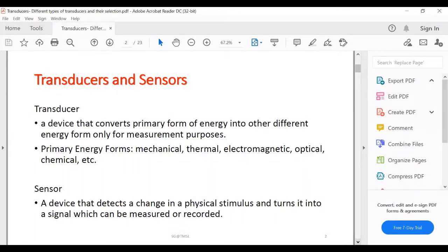As long as the transduction function is non-ambiguous, it is possible to determine the magnitude of the input variable from the electrical output signal, at least in principle. Certain other variables may interfere with this transduction process, such as the hysteresis error, the frequency response, and the baseline drift.